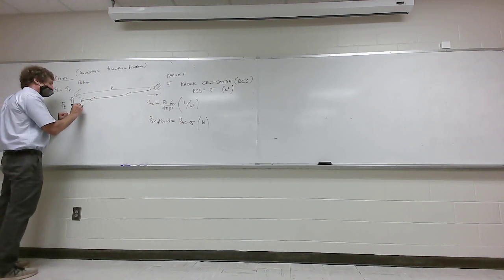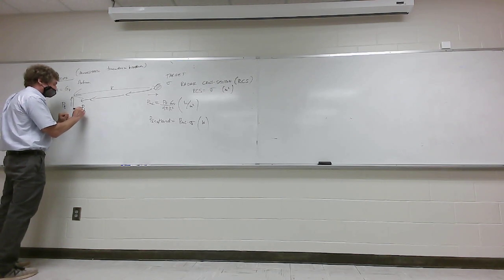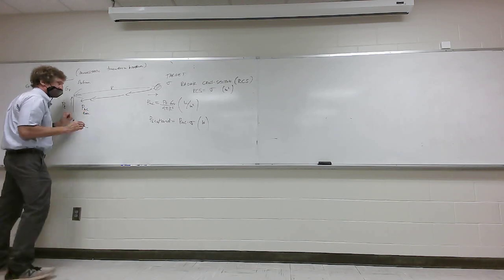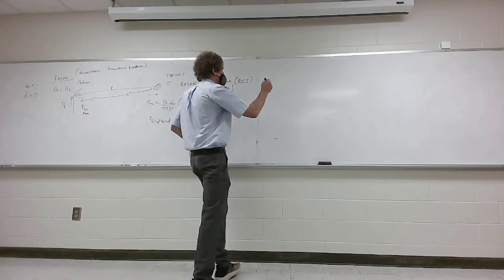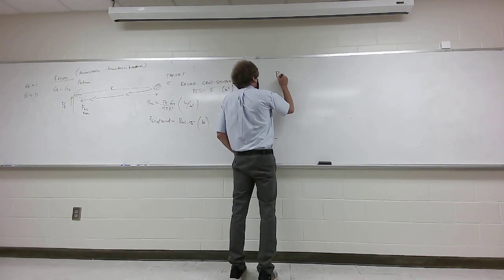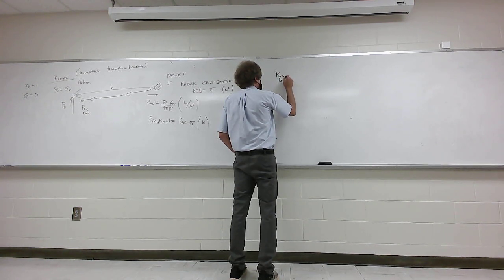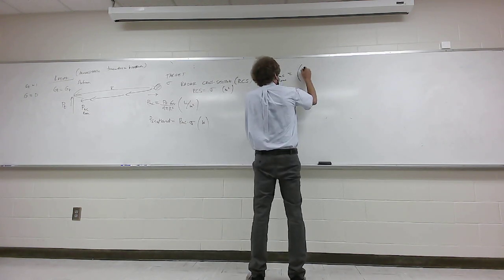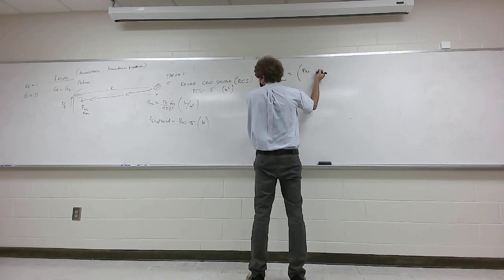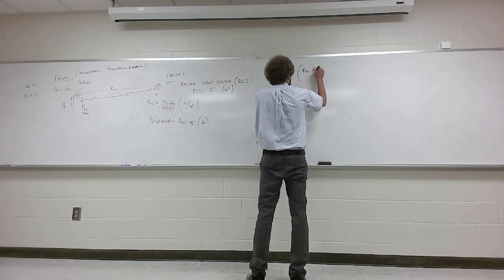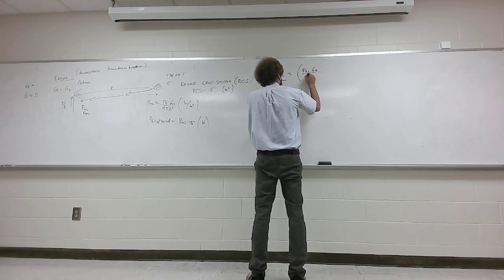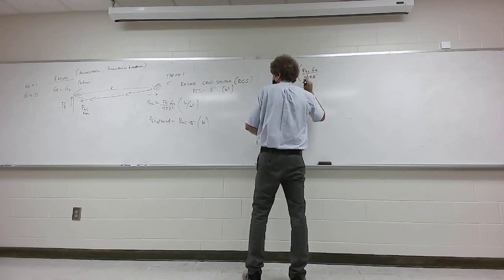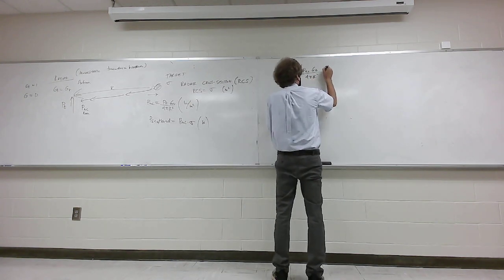Next thing we get is the actual power density incident here, and this is going to be at the transmitter. So that power density is equal to the power scattered, it's P incident right there, times gain at transmitter over 4 pi r squared times sigma.